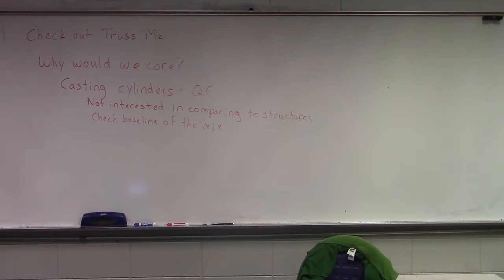So if you add more water, like say if you did an air entrained mixture, and you added more water, would you have to adjust the amount of air entrainment that you put into it? If you add more water, yeah, you would probably have to add more air entraining agent, because it would be more diluted. I would caution against recommending adding more water, because adding more water is going to increase your water-cement ratio. So what would you do then?